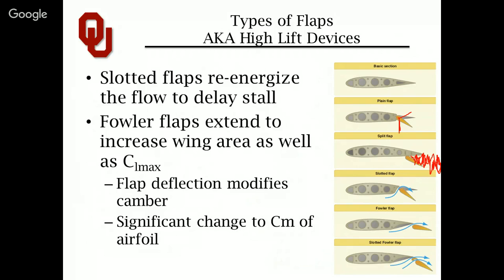So again, continuing in complexity, a Fowler flap. Now it has a very particular name. It is really just a cheaty slotted flap, because in this case they allow the gap to exist. It is just a plain flap in most considerations. Normally these will only drop down. Fowler flaps start to get into systems you might only use during landing, not really used for maneuvering, hardly ever.